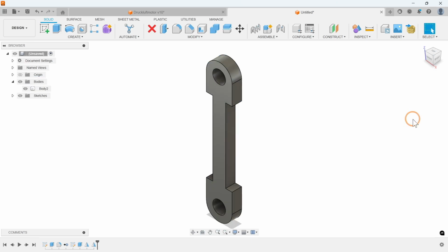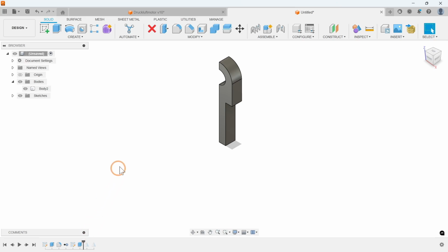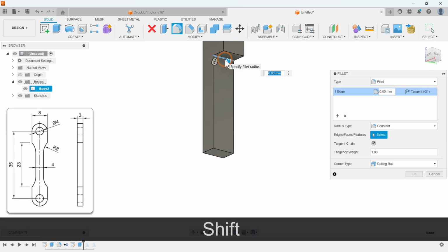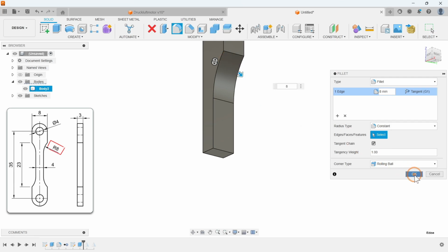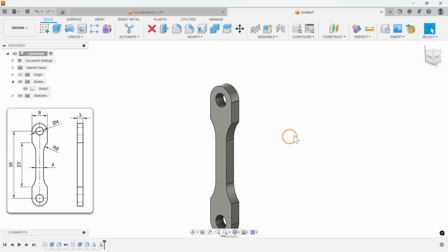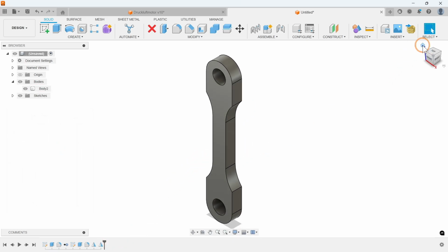We could now round off the 4 inner edges of the connecting rod. Alternatively, we can move the transition marking behind the extrusion of the quarter body in the design process and add the rounding there. If we move the timeline marker back to the end, the filleting will automatically be integrated into the mirrors. We do not need to adjust the material of the component since it is made of steel.